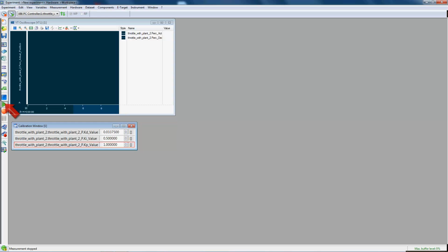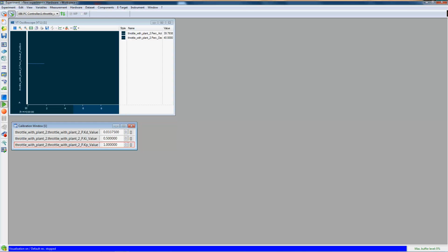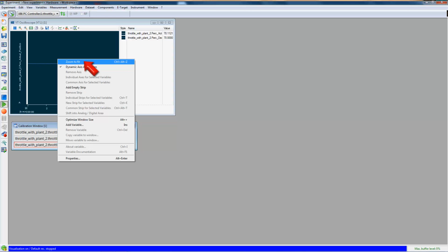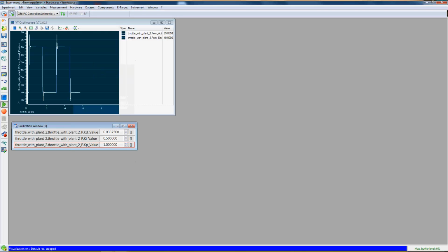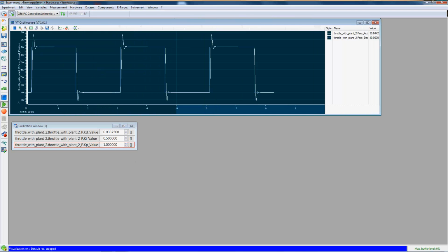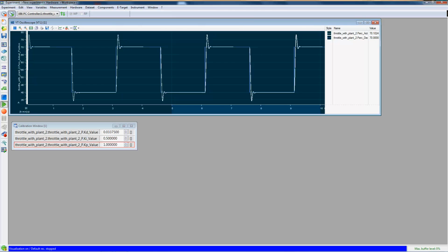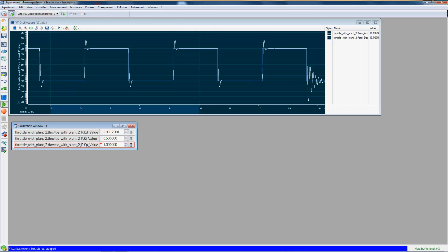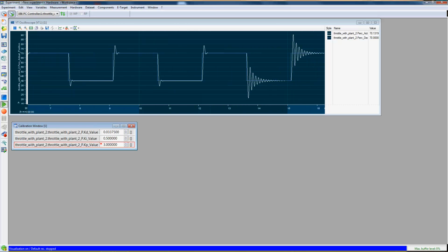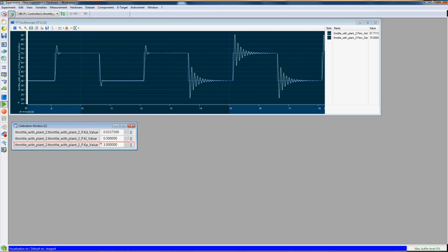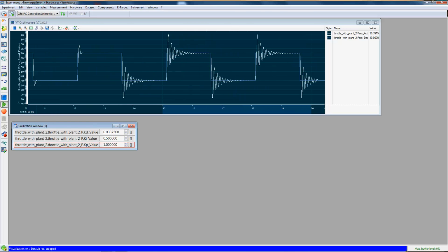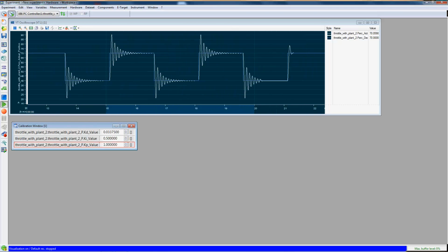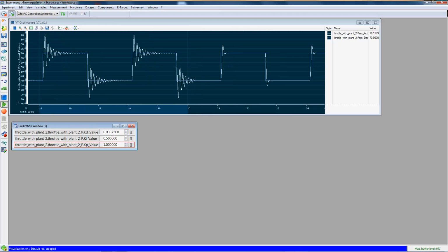Once the experiment is set up, we can start measuring. Let's zoom to fit, and we see the control simulated in scaled time. Let's change a calibration, and we immediately observe a change in the PID response. And all this without having a Simulink license.